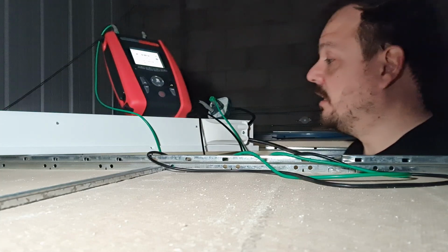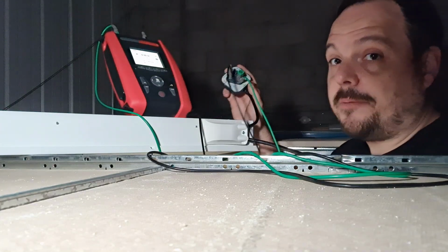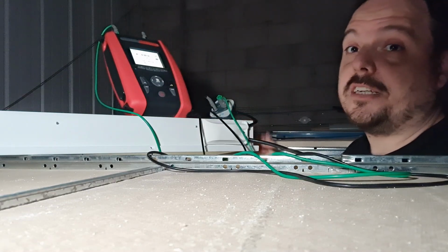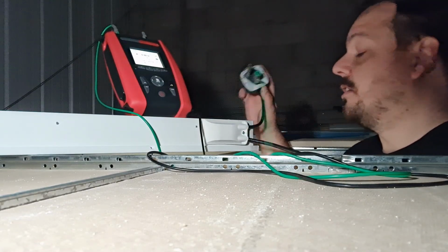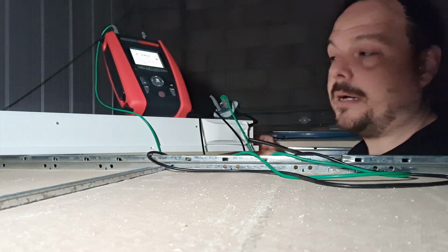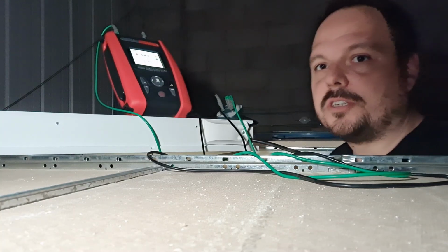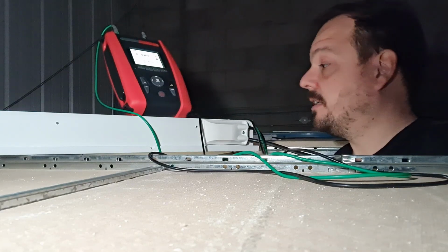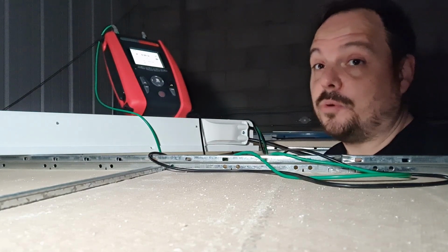And as I've shown before on other videos, we can get a live measurement of ZS quite safely at all the socket outlets. And now, because I've wired this in here at the dead test stage, we can also do that very, very safely with the Q-Tech adapter, no access to live parts, because no one wants to be up the steps with probes messing about on live terminals unless you absolutely have to, and in 99% of cases you do not have to.